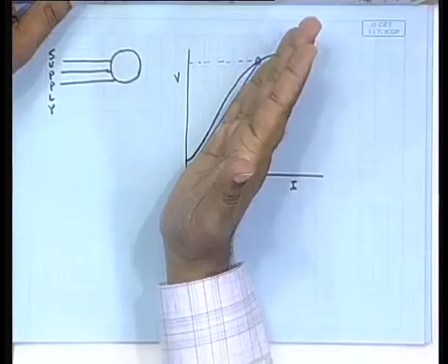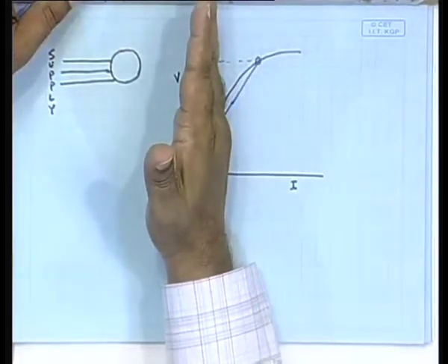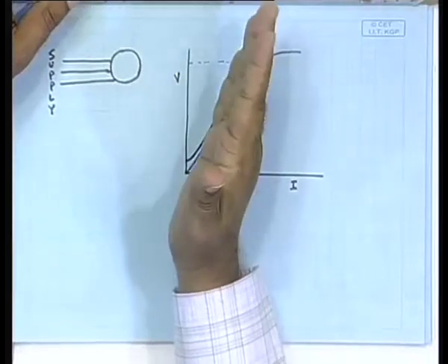Why does it happen only beyond a certain speed? That's because if the speed is low, the capacitor characteristic will be like this. Why? Because the capacitive impedance depends on the frequency. When it is rotated, yes, it generates a voltage, but that voltage has a frequency, and the value of the capacitive impedance depends on the frequency, right?